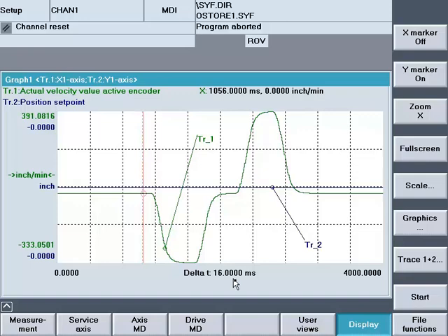It's 1 over 0.004, comes out to 250. If we follow all good signal processing theory, that means that we shouldn't count on being able to observe anything above half that, 125 hertz, because of an effect called aliasing, which is basically where signals can hide and show up as different frequencies because you were sampling too slow.